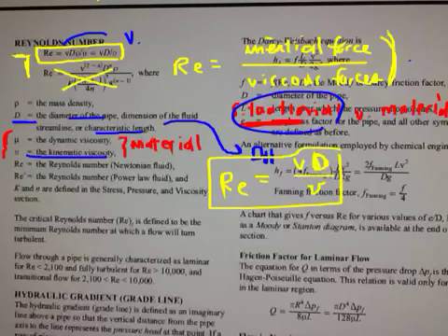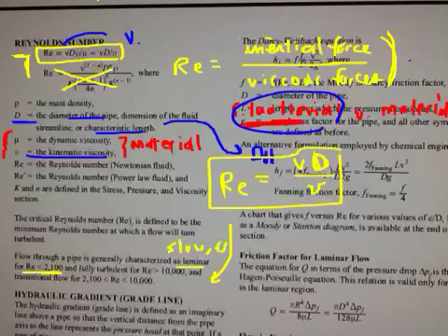And we see down here that when the viscous forces are greater than the inertial forces, we get slow flow. So, and that's the condition here where the Reynolds number is less than roughly 2100. It's characteristic of laminar flow. This is slow, even flow.